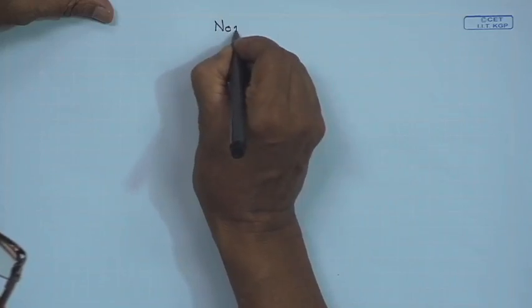So, if you go on changing the receive antenna diameter, how much is the effect on the transmit antenna diameter if I take the downlink, that is the satellite antenna. The other way is also true. Those things are in the problems. So, now let us go into another part of the subject, which is called the noise power.